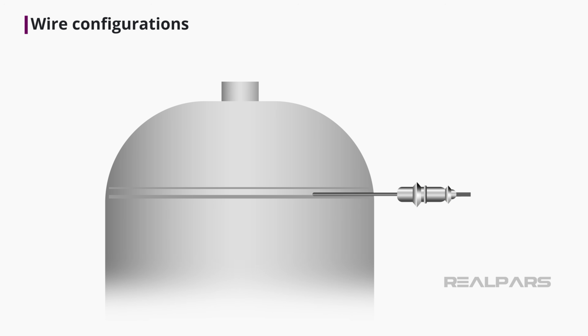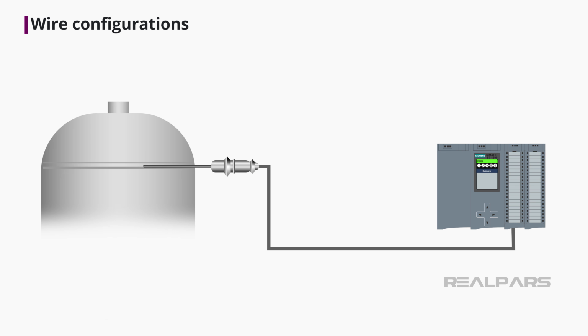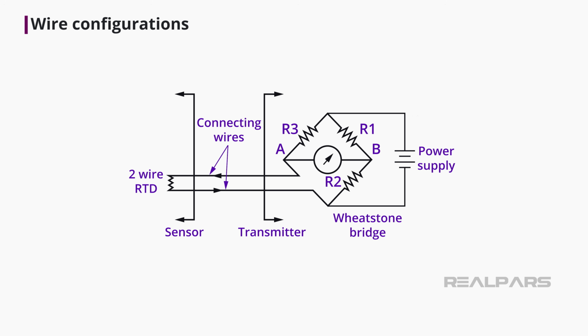As we previously talked about, the unit given by our RTD is in ohms. We need to convert this delta in resistance to a delta in voltage or current to use this signal. This is done by connecting the wires from our RTD to a transmitter, a PLC, DCS, or even a PID controller. A bridge circuit known as the Wheatstone bridge is used for that purpose.